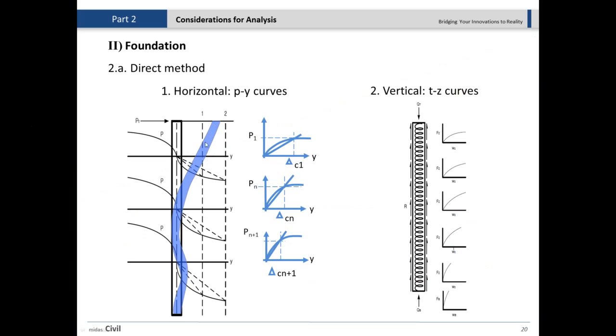You see there is a change when we have a pile and we are pushing it laterally. Here is where the curvature is changing, and we can call it a point of inflection. So probably we have the 0 moment at this location. You can just fix the structure from that point, or find where the displacement is 0, fix it at that point, and ignore whatever is below that.